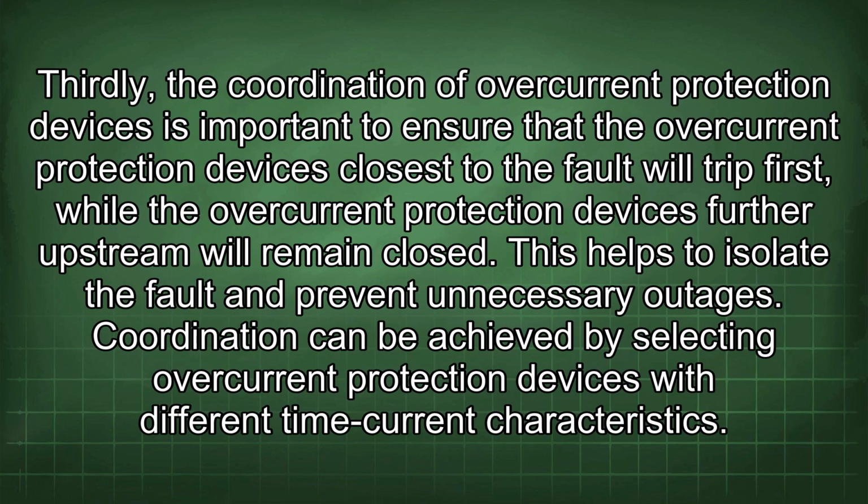Thirdly, the coordination of overcurrent protection devices is important to ensure that the overcurrent protection devices closest to the fault will trip first, while the overcurrent protection devices further upstream will remain closed. This helps to isolate the fault and prevent unnecessary outages. Coordination can be achieved by selecting overcurrent protection devices with different time current characteristics.